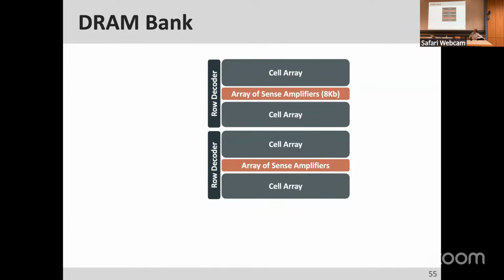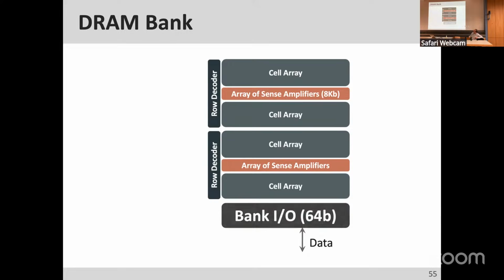That's the idea. In real DRAM, you have 128, maybe 256 subarrays, maybe more subarrays in a single bank. Of course, the number of subarrays affects your row decoder, global row decoder also. There needs to be another row decoder over there to decide which subarray you're accessing, right? That's not shown over here yet. There's a global decoder. And also, when you access a particular row, you read the entire row into the sense amplifiers, right? Because you activate all of the cells.